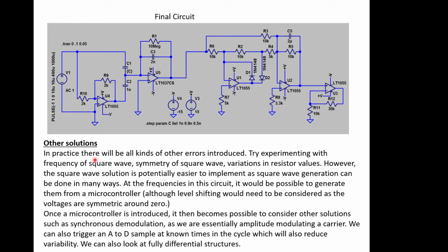In practice, you might find there's imperfections and things that start to introduce some other errors, so there needs to be a bit of investigation into that when you actually build it, because not all circuits are the same when you build them. And it may well be in this case you have to go back to the customer and say, look, your 500 microvolt spec for a zero input is actually really tight. Maybe you can relax it a bit. Otherwise, I'm going to have to spend a lot more money and making this system perform a lot better. And if that spec turns out to be just something they've written down because it was a good idea at the time, by changing that spec you can actually increase or decrease the cost of your system.